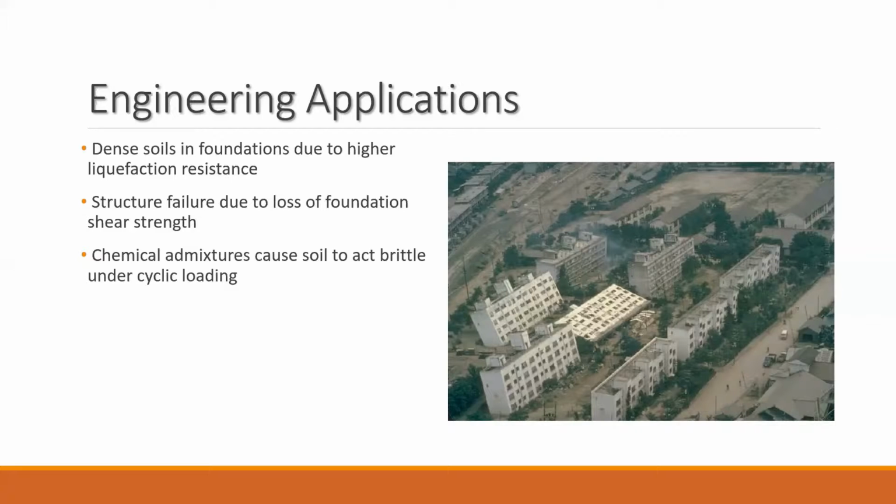Another solution to increasing the shear strength of soil foundations is the addition of chemical admixtures into the soil. However, these admixtures have been found to cause the soil to act excessively brittle under cyclic loading, and hence don't increase performance as they are supposed to.